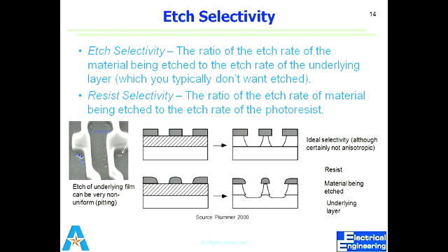But usually we always use an etchant that is selective to a certain film. If you have two films, you always go for two separate etchants. If in a certain application I want to etch my substrate, I will use one etchant to remove that film and another etchant to remove that substrate, because, as I told you, selectivity is not ideal.